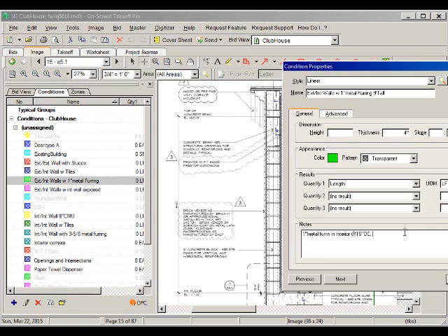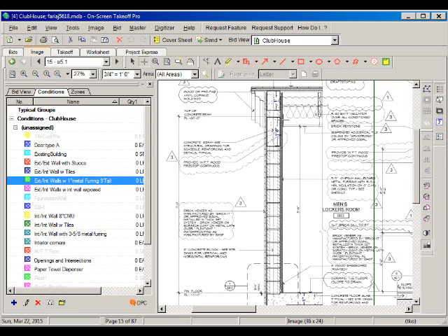So I am going to make in the note the wall is 9 feet tall, and the suspended ceiling stops at 8 feet 6 inches. Really, the difference is not too much, so some estimators may want to assume the paint goes all the way to the same 9 feet, and then just consider this small portion as part of the waste. So then the waste factor will be slightly smaller.